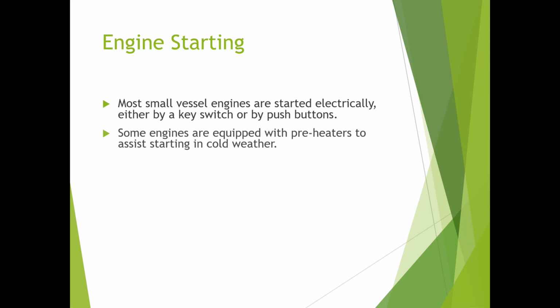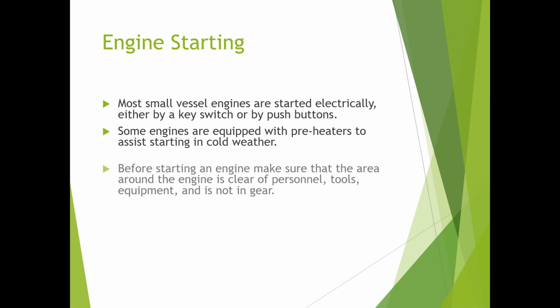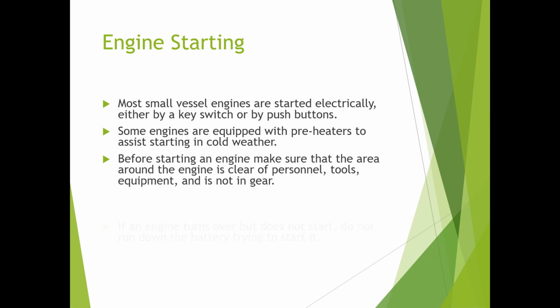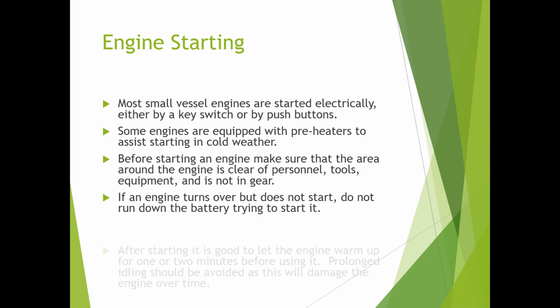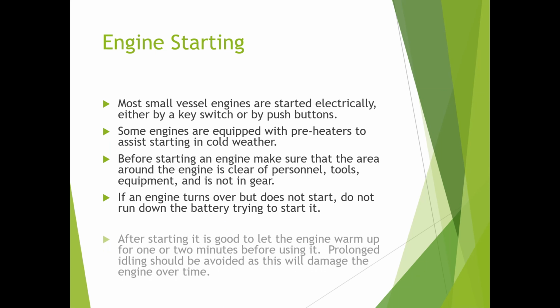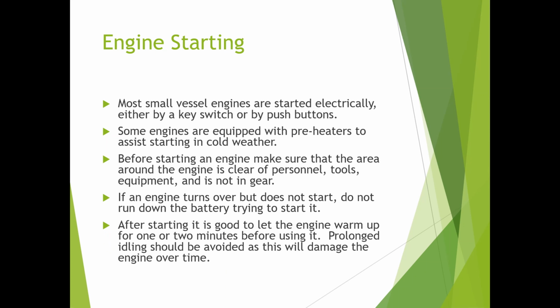Before starting an engine, make sure that the area around the engine is clear of personal tools and equipment, and that the engine is not in gear. If an engine turns over but does not start, do not run down the battery trying to start it. After starting it, it is good to let the engine warm up for 1 or 2 minutes before using it. Prolonged idling should be avoided as this will damage the engine over time.